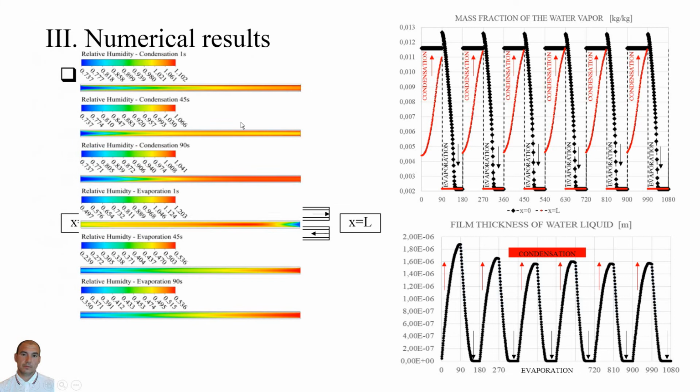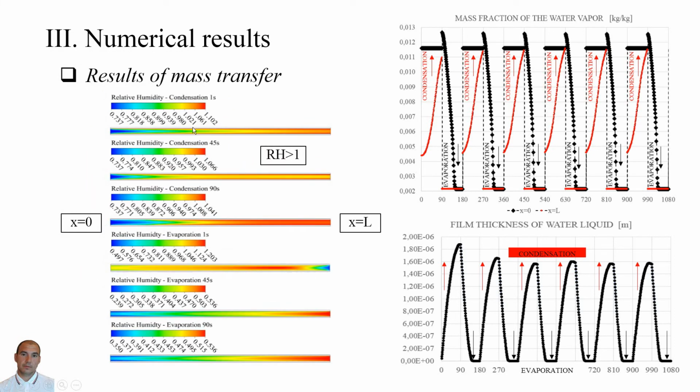The values of the relative humidity greater than 1 specify the process of condensation near the wall and in the volume of airflow during the heating period. After the heating period, the process of evaporation during the cooling period starts. Because the source of water fog formation is missing in the model, it can be assumed that values of the relative humidity greater than 1 are an indicator of the existing phase change and fog in the volume of airflow.